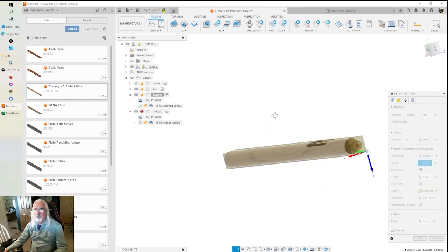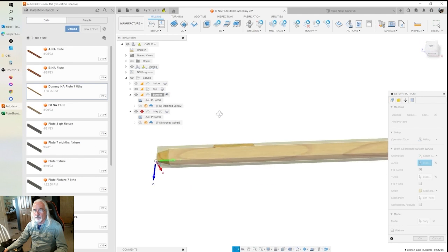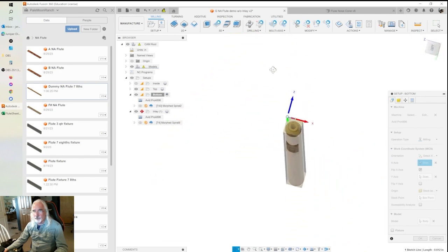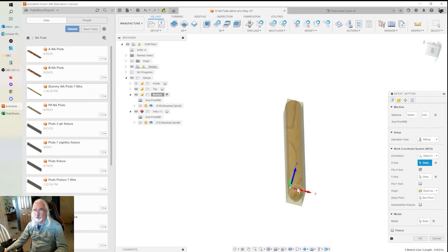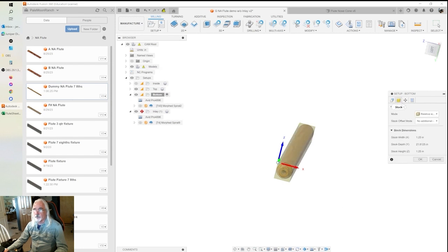And like I said, if we did a join when we did the mirror, then it's just going to be that one block. You want to make sure you set your box point to the bottom side with the Z pointing away from the bottom, or up. That should make sense. Same things on the relative size, no additional stock, and give it a name. Flute bottom.